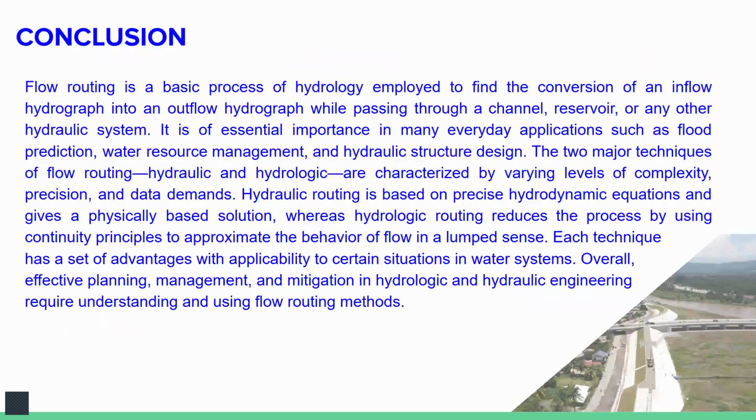So I therefore conclude that flow routing is a basic process of hydrology employed to find the conversion of an inflow hydrograph into an outflow hydrograph while passing through a channel, reservoir, or any other hydraulic system. It is of essential importance in many everyday applications such as flood prediction, water resource management, and hydraulic structure design. The two major techniques of flow routing are hydraulic and hydrologic, which are characterized by varying levels of complexity, precision, and data demands.